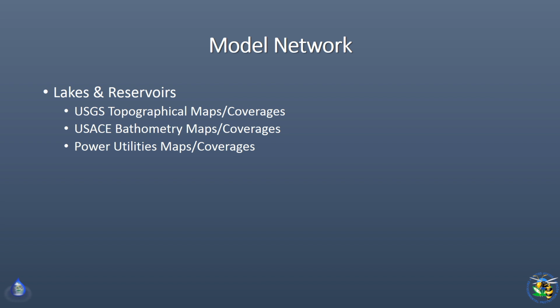For lakes and reservoirs, again, you're going to be counting on topographical maps, bathymetry maps from the Corps of Engineers, if it's a Corps of Engineers managed reservoir, or Tennessee Valley Authority, or whoever is managing it. Or you could go to power utilities. They have maps and coverages that's typically found with their FERC licensing when they need to go through that. So you can go to those individual entities to get both topographic and bathymetric maps of your lakes and reservoirs.